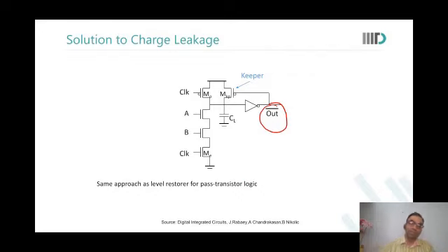As we talk about cascading gates, there is a complexity in cascading the gates. Someone pointed that thing out. We'll talk about it in a little. As we will talk about it, you will realize that we cannot have input transitions going from 1 to 0 in a dynamic gate. We said only one transition is accepted. What is also important to realize is that that transition has to be a rising transition.